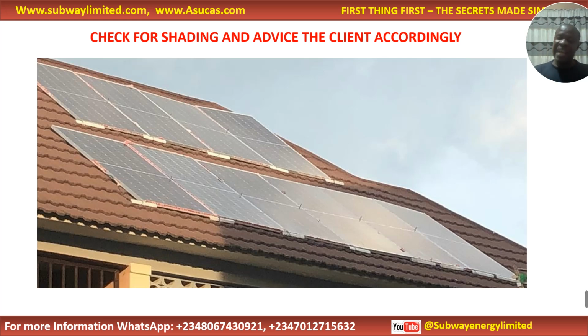So like this one, check for shading and advise the client accordingly. Please, this is not acceptable in the solar industry. This solar panel is shaded, irrespective of the fact that it might be shaded for 2 hours, 1 hour. Energy loss is money loss. We don't allow this in the solar industry. Energy loss is money loss. Guard against it and your solar system installation will not suffer. Like this one now, how many solar panels did you use? What was your storage? The hours that this panel is shaded, it is not producing as it's supposed to.